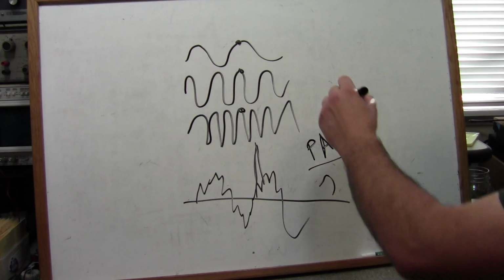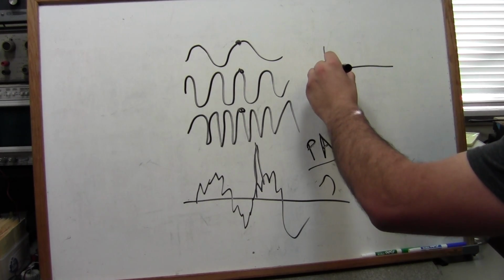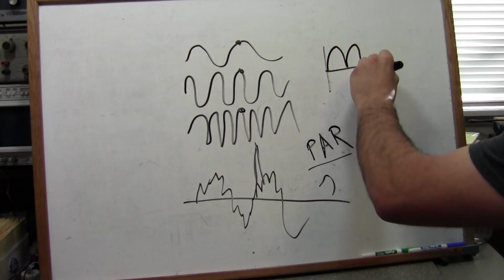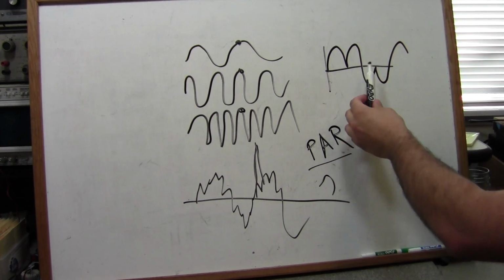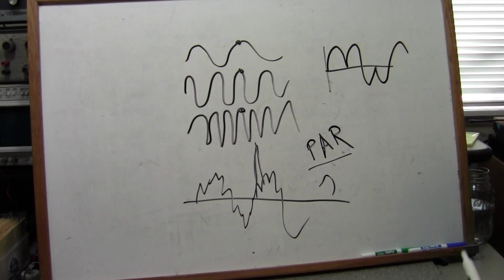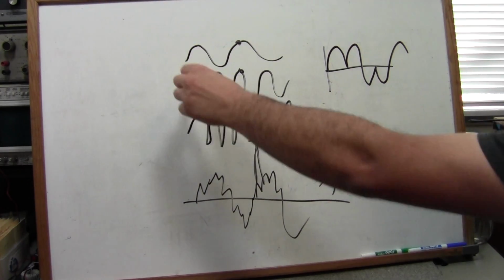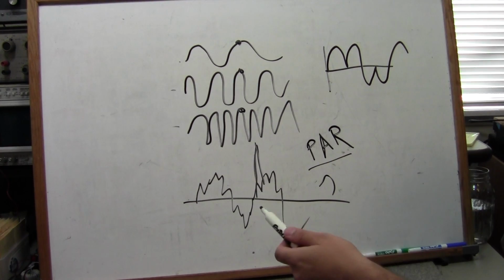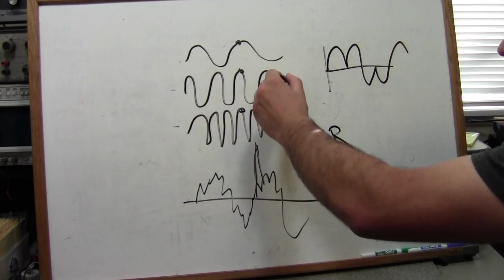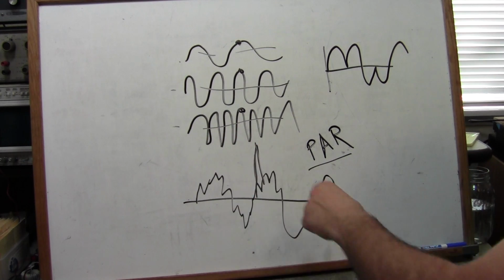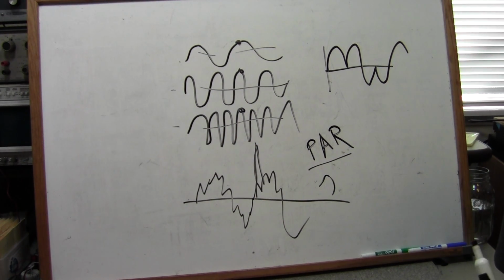For example, if you were just doing QPSK, as you're modulating it, the amplitude never changes, it's just that the phase changes. But since you're modulating each one of these carriers in some way, be it BPSK or QPSK or some multiple QAM, and then summing all of these carriers together, the output can be non-ideal like this. And there's a multitude of different ways that, if you very carefully code it, or by having different combinations of these carriers, you can reduce this and improve the peak to average ratio, but it's an intrinsic flaw in the system.